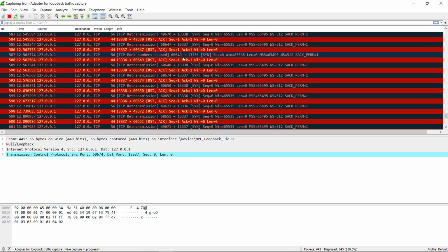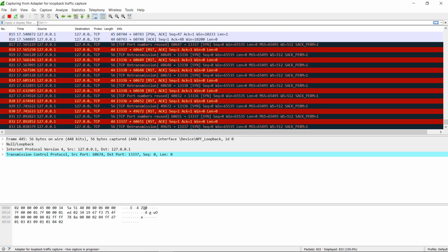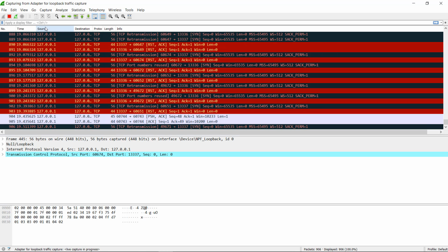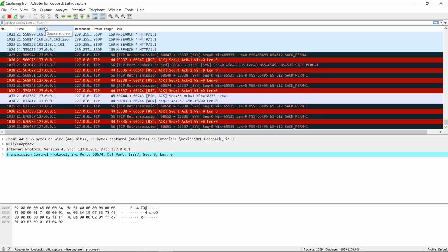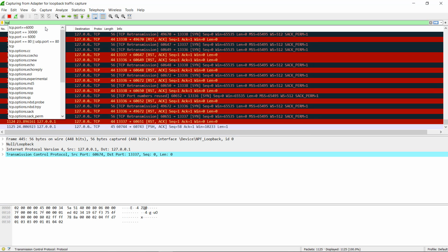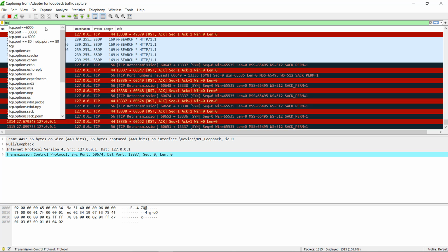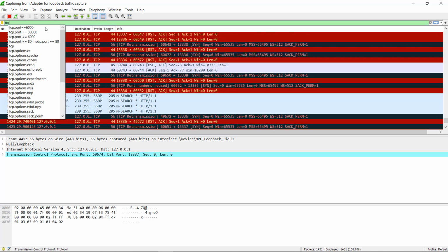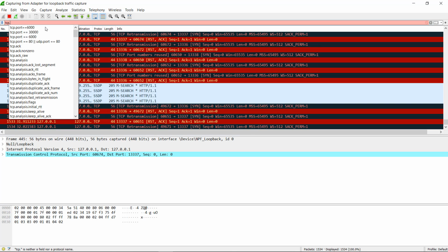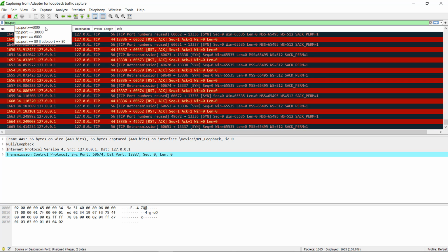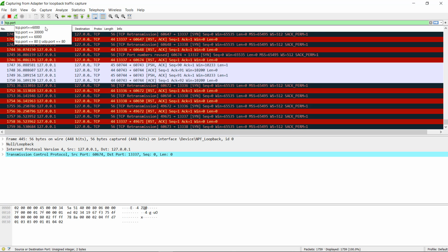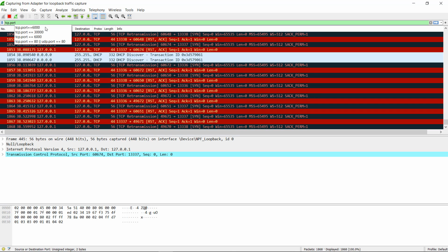So because these are not relevant for the MCD application, I'll just quickly do a filter. So my filter is, because I'm using TCP for my interface, so I'll just click TCP, and I also use the port 6000 to monitor the mapping of the signals through this port.